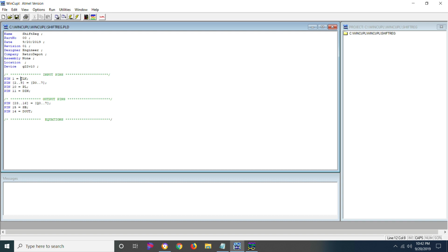Let's assume it's 9600 baud because it's a very popular baud rate. And on the other input, you have your chip select. Your output is going to go to the clock pin. So both of them would have to be high for the clock signal to be high. But if either one of them drops low, that is going to cycle the output and thus the clock to a low state.